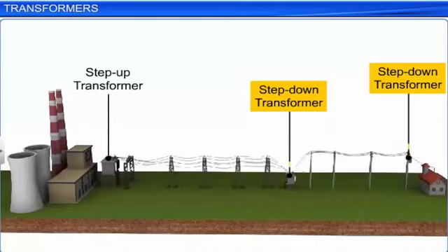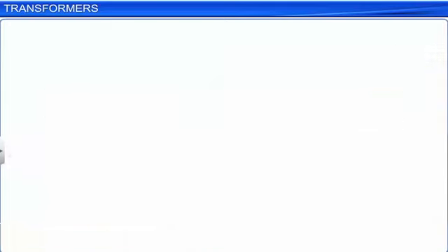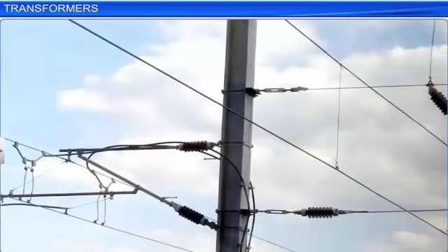There is a practical upper limit to the voltages we can use for transmitting the electrical energy through the transmission lines. Excessive voltages can ionize the air around the transmission lines. This in turn can create a conducting path to the ground or other objects near it, and also can possibly cause damage to life and property in its vicinity.